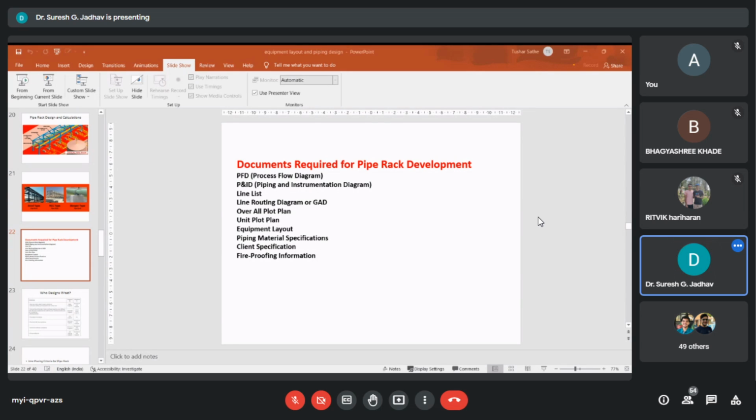sketch. And tank outlet. Tank outlet piping can either penetrate the dike or pass over the dike in case the minimum liquid level in the tank could cause cavitation.